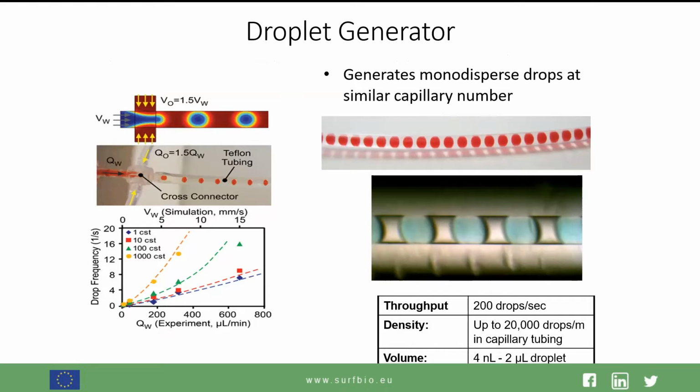The droplet generator is usually quite an easy device. You don't need special chips or pumps. You can just combine a few flows, one of them oil, another one water. In that case you can produce droplets. If you premix well with another substance, you can cover them, and you can increase the frequency by increasing the speed of your pump, which influences the size, shape, and so on.